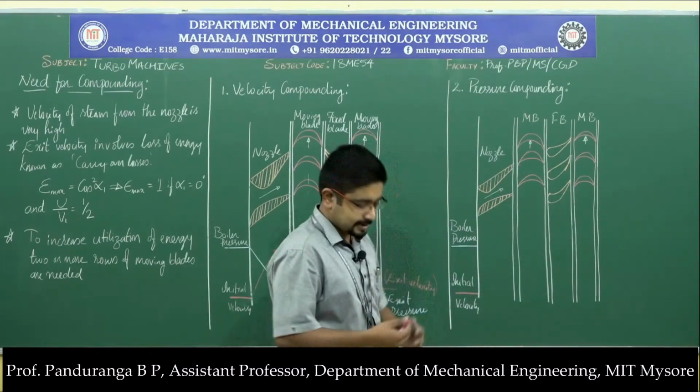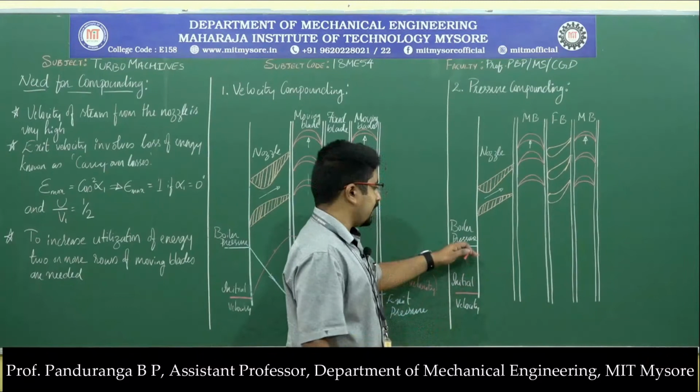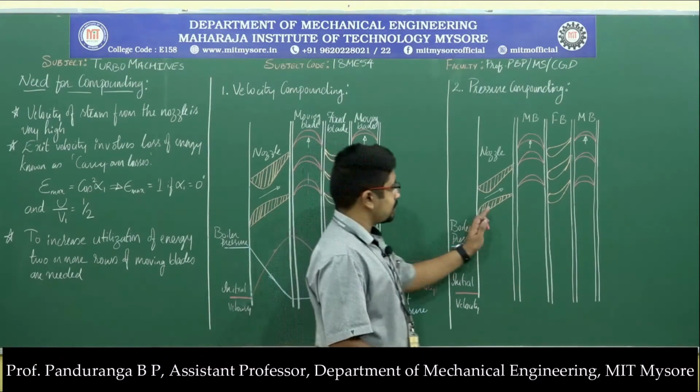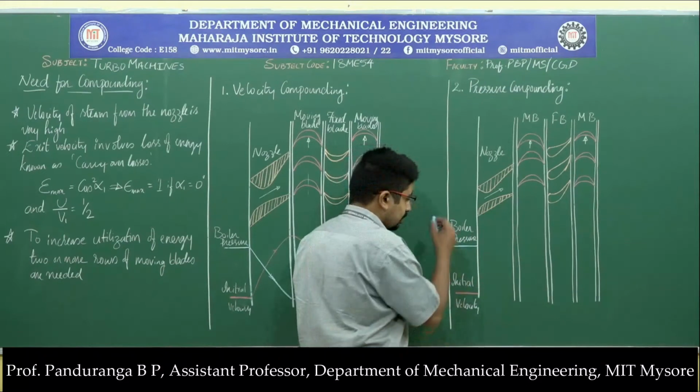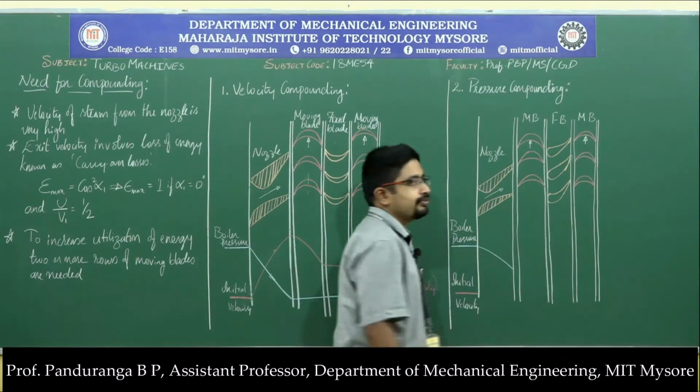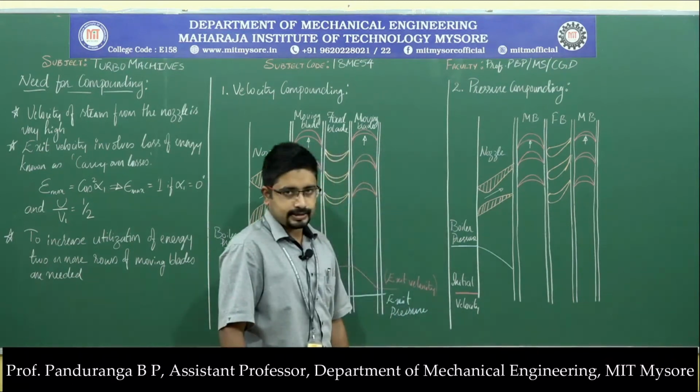So now let us see the working of this. Here we have the steam entering the nozzle at boiler pressure, and as it passes through the nozzle, a certain amount of pressure energy will be converted into kinetic energy.